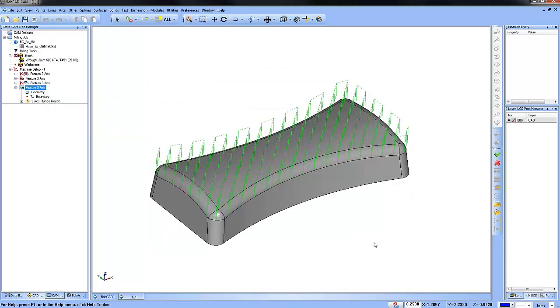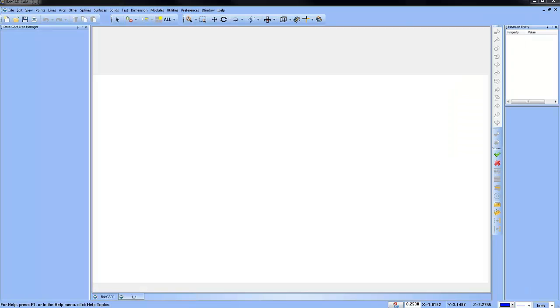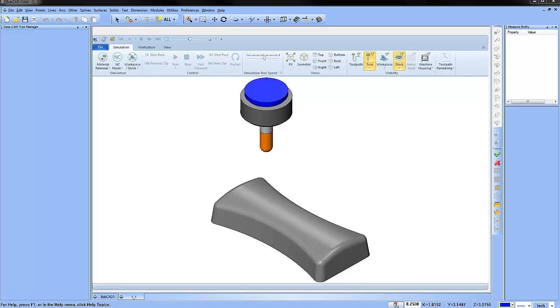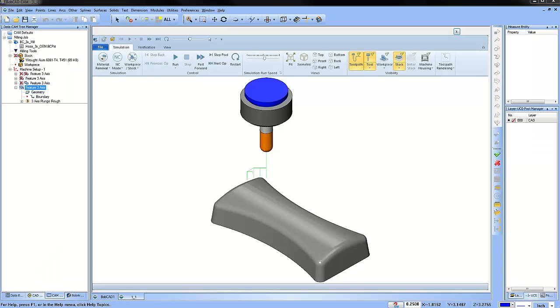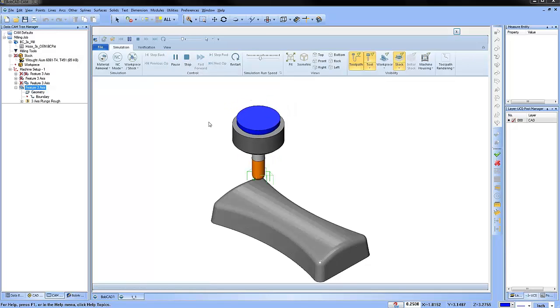There was another question that came in. Why would I on purpose use plunge to rough out material? Feeds go down. Marcus had a question about plunge roughing. Plunge roughing is a strategy or a technique for removing material. In harder materials, it comes up more often. I guess this was kind of more popular before the adaptive toolpaths have come out.